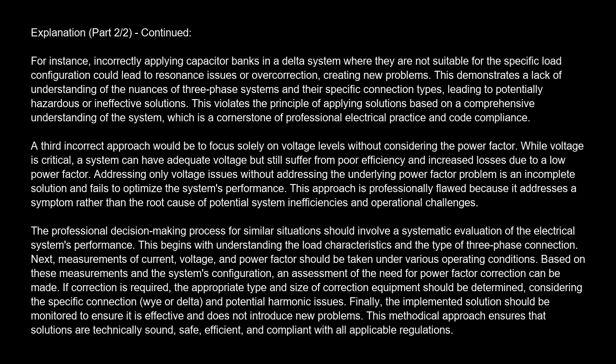A third incorrect approach would be to focus solely on voltage levels without considering the power factor. While voltage is critical, a system can have adequate voltage but still suffer from poor efficiency and increased losses due to a low power factor. Addressing only voltage issues without addressing the underlying power factor problem is an incomplete solution and fails to optimize the system's performance.